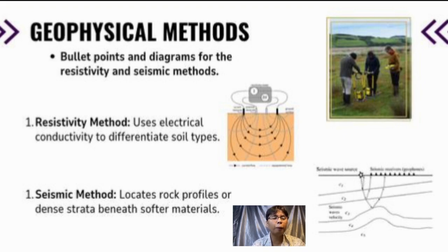Seismic method. This approach measures how sound waves travel through the ground. It is particularly effective at locating rock layers or dense strata beneath softer soils, which is essential for assessing stability. Both methods provide valuable insights that help engineers design a stable and reliable road structure.